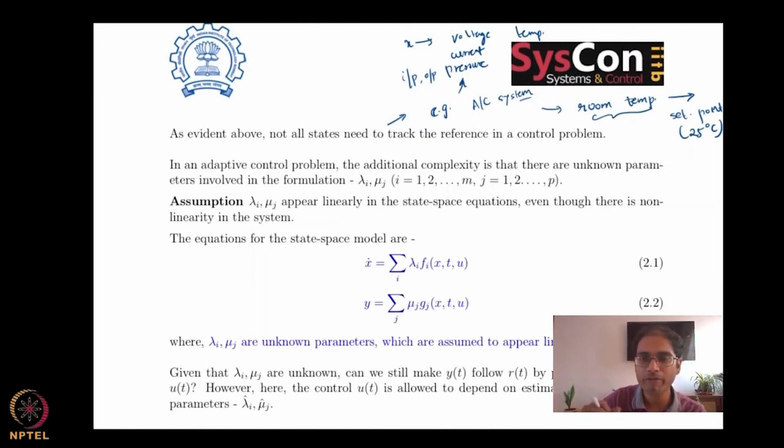Of course, if you wanted to make a very fancy air conditioning system, which actually does what it promises, then the AC will have to come with many temperature sensors that have to be mounted in all corners of the room. And then it somehow maybe takes the average of that to create the output temperature and uses that to control the air conditioner better.